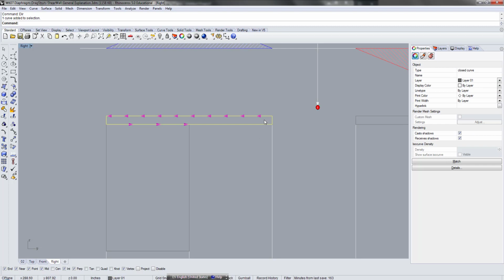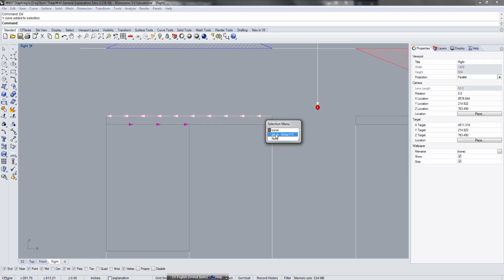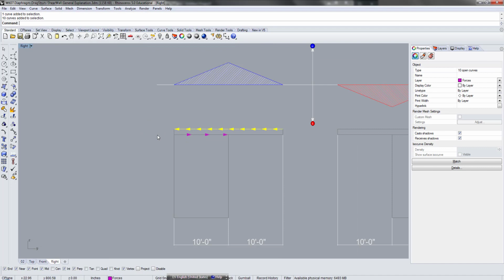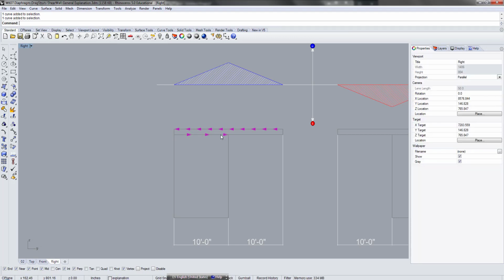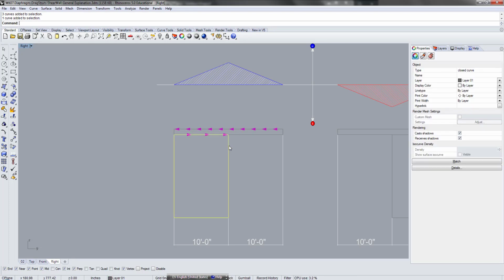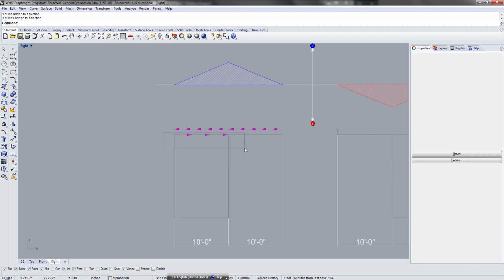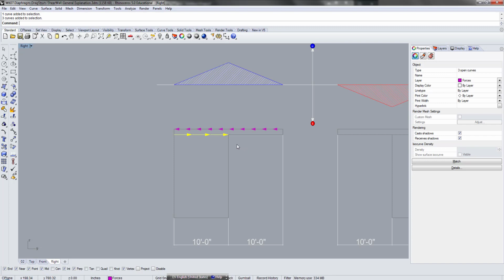So this beam is being pushed in this direction because the lateral force is going this way by the floor above, and it's being pushed back by that much force by this shear wall. So the total amount of shear between this and this is the same, but because the linear length was half, the intensity here per linear foot was double, right? So this is more intense than the top.